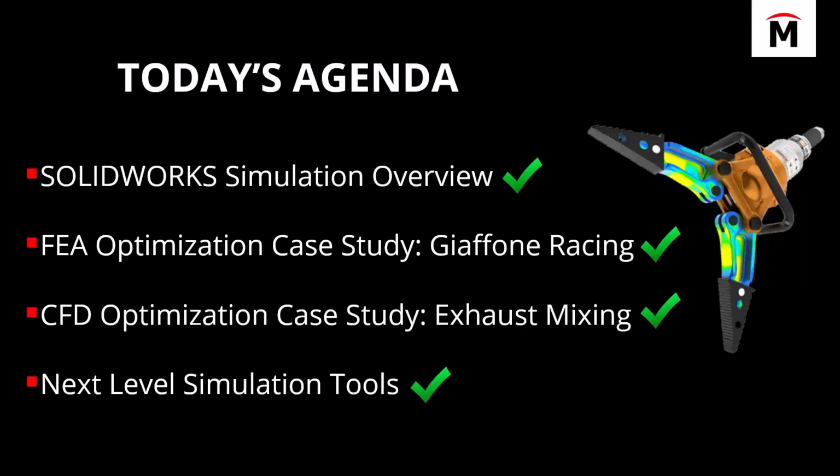Yeah, that is a good question. It's a little dependent on which simulation tool you're running. If I start with the first one I ran today, SolidWorks Simulation FEA, RAM and CPU speeds are up there. I usually find if I devote more than 8 cores to SolidWorks Simulation, that's where I start to get a lot of diminishing returns.